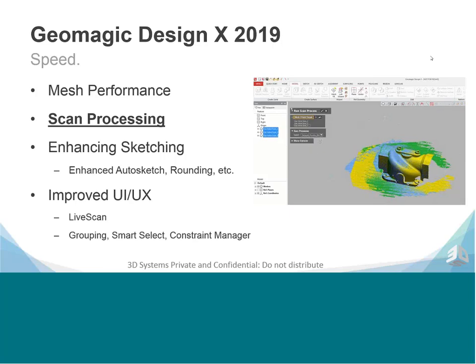And this includes things like selecting areas, deleting them, doing merge, as you can see on the screen. It includes region grouping. It also, of course, includes some portions of the exact surfacing. So if you wanted to quickly process a bunch of contour creations, you could do that with a bunch of scans. And it's all done within the product, or of course you can run it as a batch process, as you could always do with DesignX. But this will allow users the ease of use to quickly run what they want with one click.